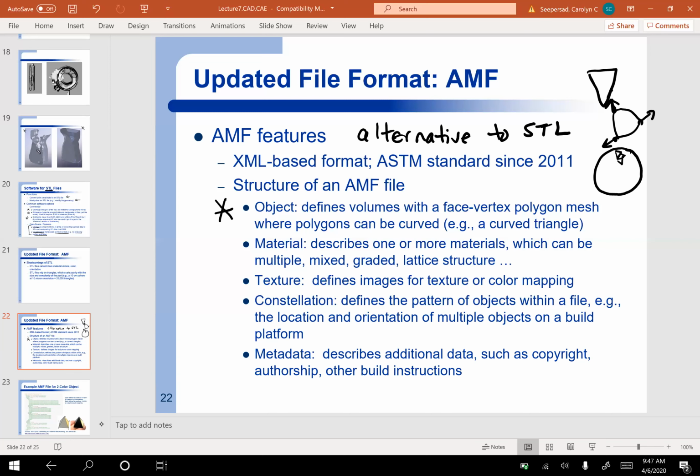So then you can actually represent a curved surface on a sphere with curved triangles, which means you have fewer triangles, even though each triangle now has 3 vertices and 3 unit normals, one at each vertex, instead of just 3 vertices and 1 unit normal for a planar triangle. So for a planar triangle, we've got 3 vertices and 1 outward normal. For a curved triangle, we've got 3 vertices and 3 outward normals, one at each vertex, sorry. So it's a little bit more information, but that's well worth it because you could use far fewer triangles to represent something like a sphere, right?